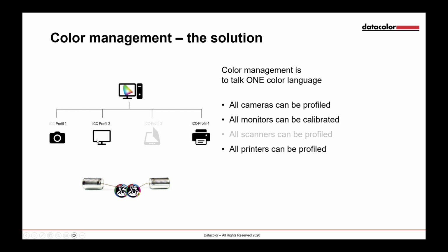Due to the aging effect on monitors, have a look if the monitor has a counter for the hours of usage. You will say, okay, this is important. And you have a fading effect because the filters and the backlight will fade over the years.